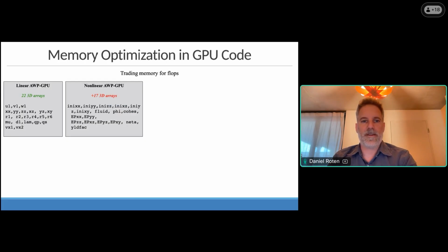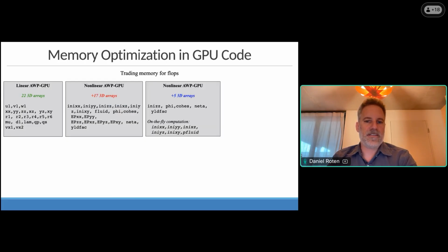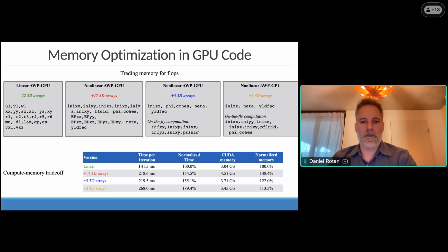So what we did instead, when we figured out that when you apply the Drucker-Prager yield condition, you actually establish a yield factor called R, which tells you by how much the stress deviator yields. We only computed that at the position where the normal stresses were defined and interpolated only this yield factor for the other subgrid positions. And we found that for a scenario simulation like the ShakeOut I showed before, those 2 solutions are basically indistinguishable. With that solution, the computational cost of adding plasticity is only about 65% more than a linear simulation.